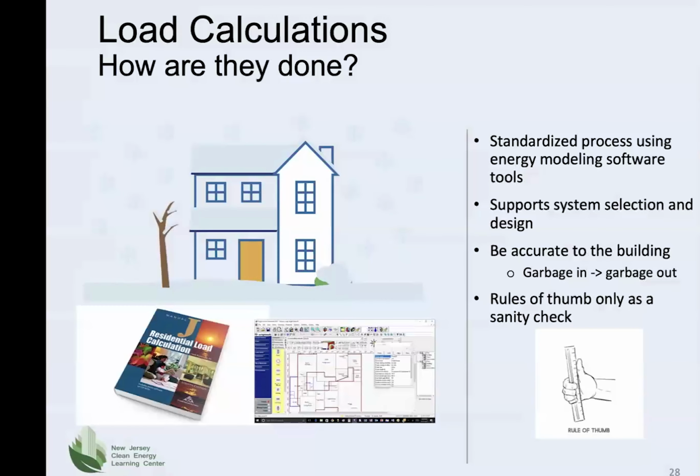The Air Conditioning Contractors of America, ACCA, is the author of a manual entitled Manual J that describes the procedure and equations that are used to calculate heating and cooling loads for single-family freestanding homes. Although the calculations can be performed manually, a software program is usually used in conjunction with Manual J. The ACCA has a list of approved software programs, and only those programs meet ANSI standards and also many of the building codes in the United States.